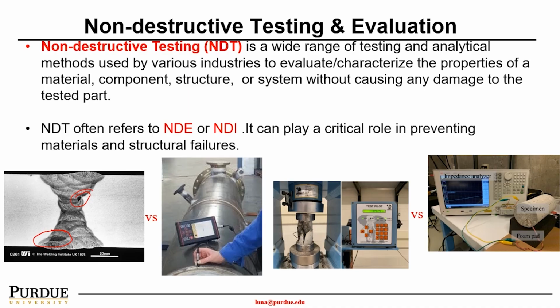So when we test to identify welding defects in service, rather than doing this type of image processing, we could use ultrasound, as shown here. By sending an acoustic wave and analyzing how the wave propagates and reflects, we can image the welding quality and see whether there are any voids.